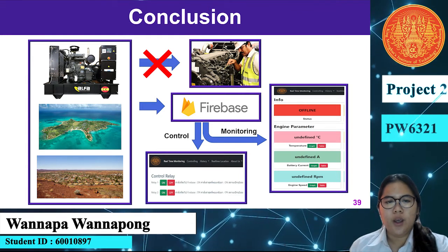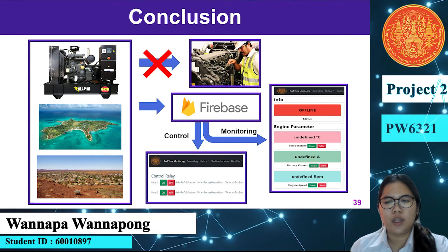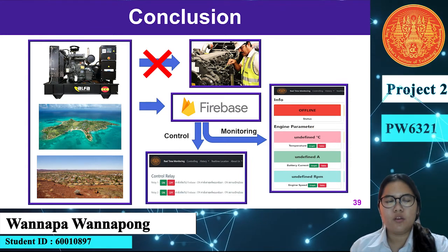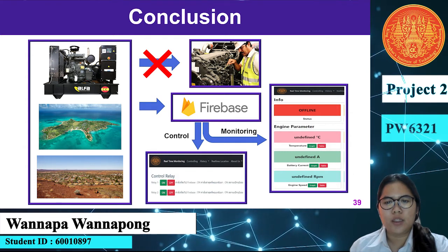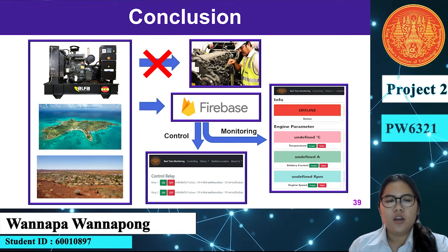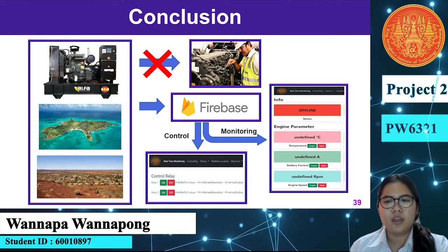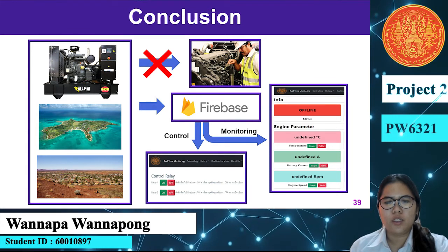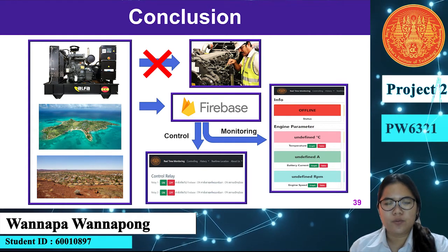Third, the device is able to save one parameter to a micro SD card instead of disconnecting from the internet. Fourth, the device is able to notify one abnormal status of the generator set via the Line application. Fifth, the device is able to control the operation of generator sets remotely through the internet by website, or by phone signal system using the 2G signal via SMS sending.